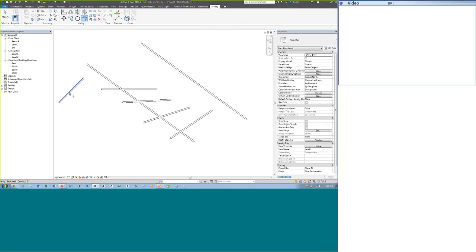You start the command, you pick the sides you want to keep, and you're done. Okay. Trim/Extend Single: start the command, pick the object you wish to use as the cutting edge, and then pick the entity you want to keep, picking the side you want to keep like this, and it trims back. If you do the command again, and before you pick the first object you hold the Control key down, you can basically do trim multiple. And then if you do trim extend multiple, you're picking an entity to extend to, and then you pick the entity, and you'll see that it does that.